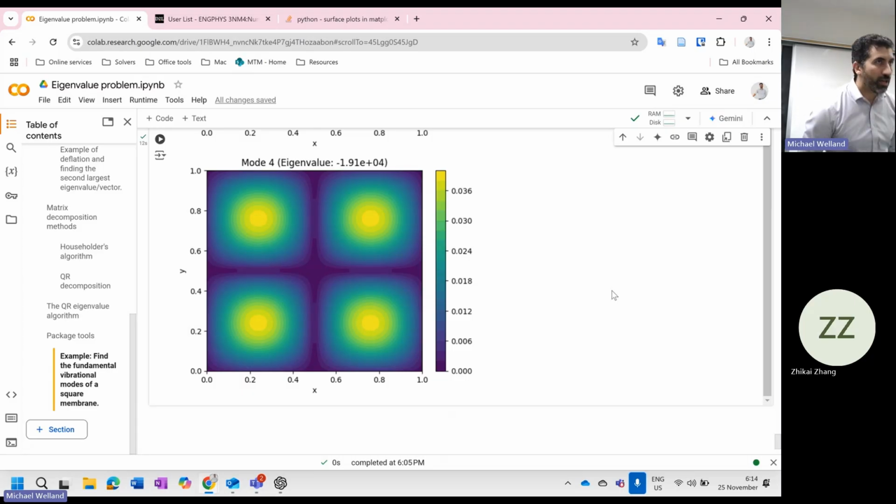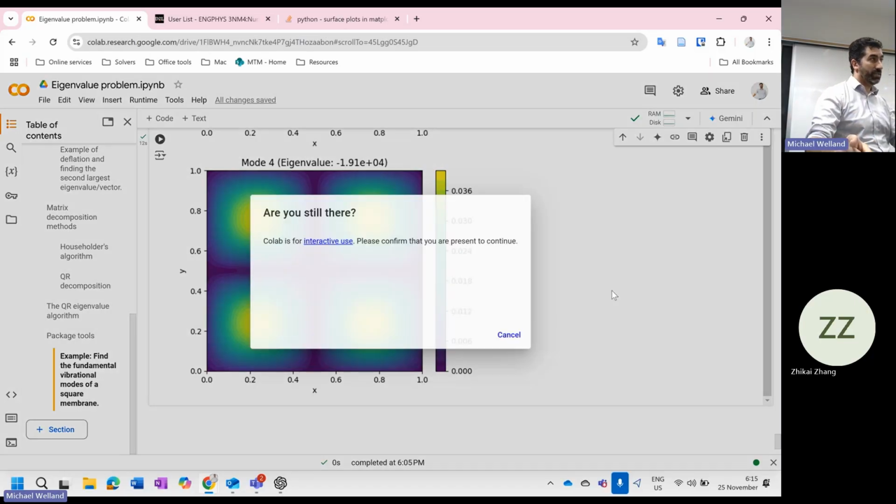And the idea there, you guys know how, if you have a signal, you do your Fourier transform. That Fourier transform works because you have sines and cosines. Sines and cosines are eigenfunctions, and they are orthogonal. So what you can do is calculate what your signal is in terms of these eigenfunctions, your Fourier series. And then you can do magic on that. You can analyze the frequency spectrum, you can put it into solvers, you can get all kinds of things out of it. Turns out the same thing is true of these types of problems.